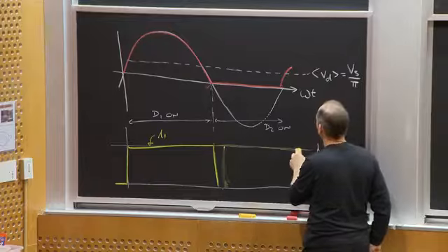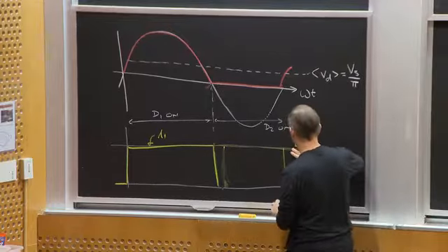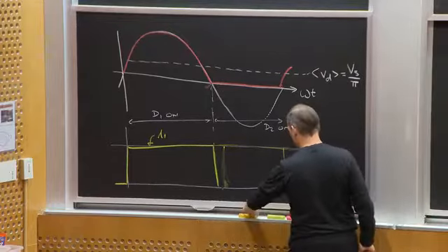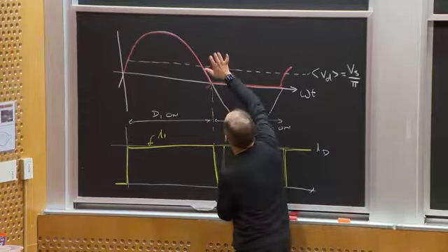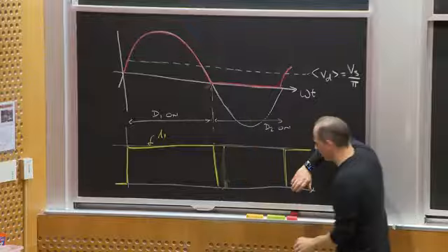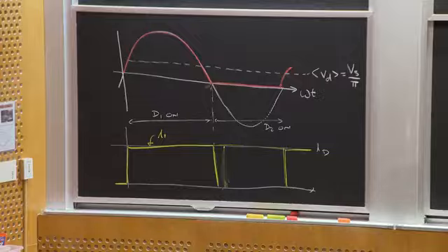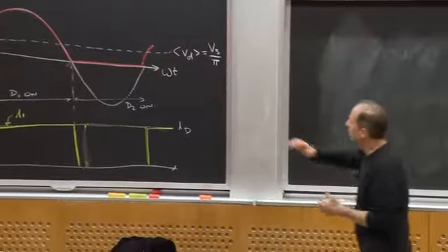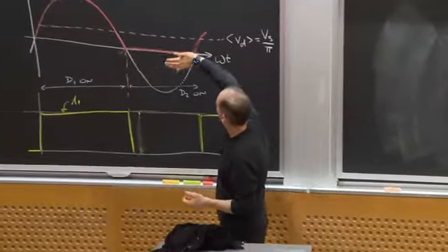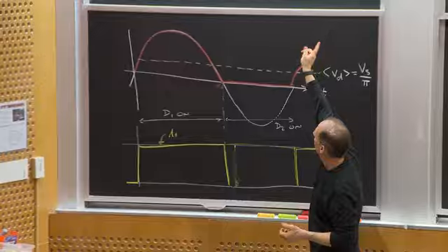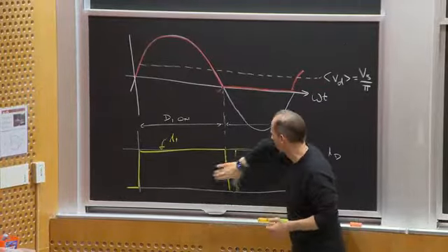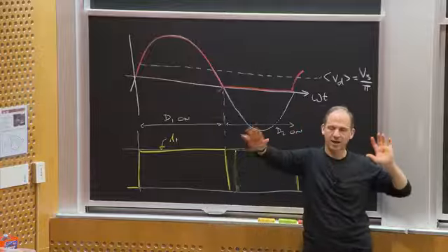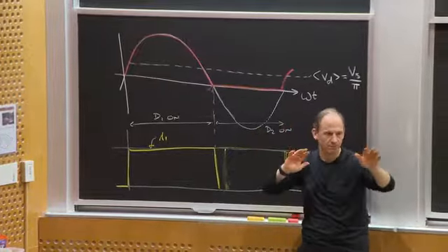Okay, so here's like this, okay? And so they just alternate carrying current for half the cycle. First diode 1 carries all the current, then diode 2, then diode 1, and so forth. Okay, and that's sort of the conclusion we came to about what's happening with the circuit. So basically, in the first half of the cycle, D1 carries the current, and then immediately the current switches to diode 2 in the second half of the cycle and just keeps flopping back and forth, commutating back and forth. Okay?